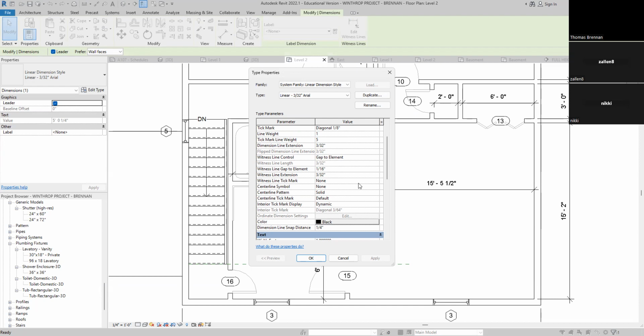Okay, you gotta click in white space. Well, first of all, click on, okay, all right, here, Steve, you try it. First you click on 2 points you want. Here to there, good. Then pull over to the right, click in white space, there. You gotta drop it, it's totally contrary to what you would think. I've been fighting with that. Yeah, that's how it is though. For dimensions, you just gotta click in white space to drop the dimension. Very counterintuitive, I know.